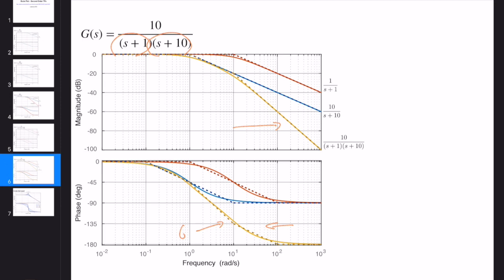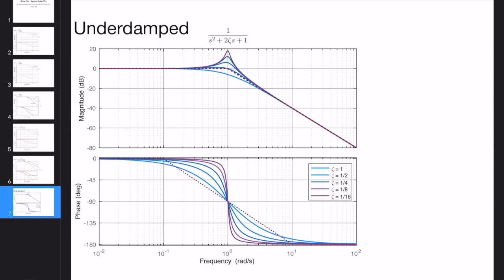So the take-home message is the approximations are pretty good for overdamped systems. These asymptotic approximations were already good for first order systems. For critical damped systems, it was okay. Now we will see what happens when we have an underdamped response, when psi is less than 1.